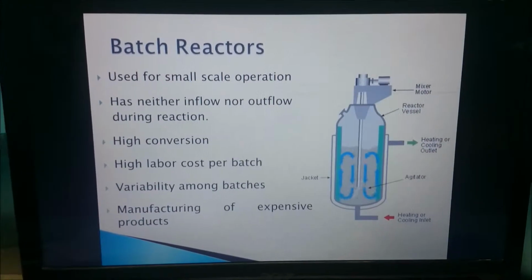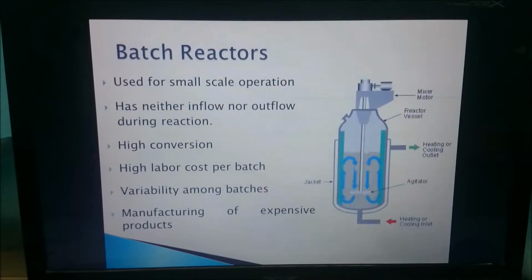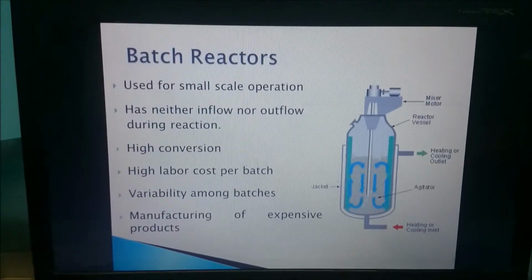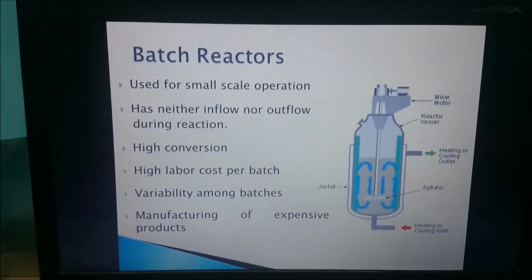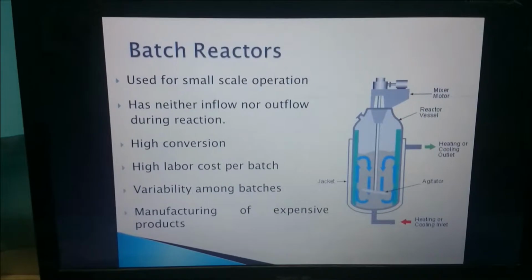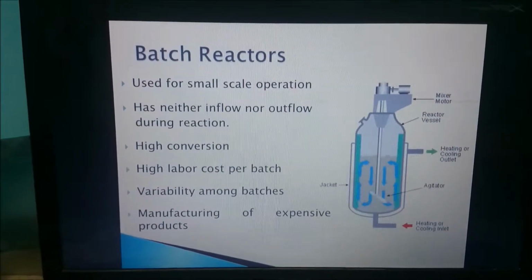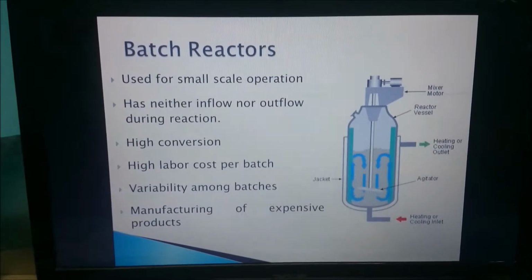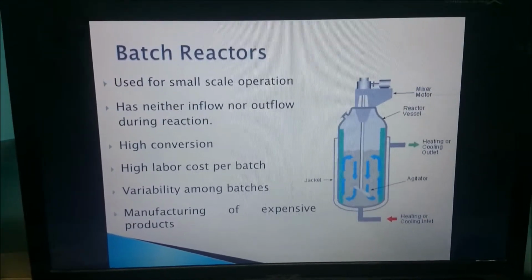Okay, batch reactors are used for small scale operation. They have neither inflow nor outflow during reaction. Although these reactors can give you a high conversion, the drawback is that they give a high labor cost per batch, and there is variability among batches. It is used for manufacturing of expensive products. Usually this kind of reactor is used in pharmaceutical industries.